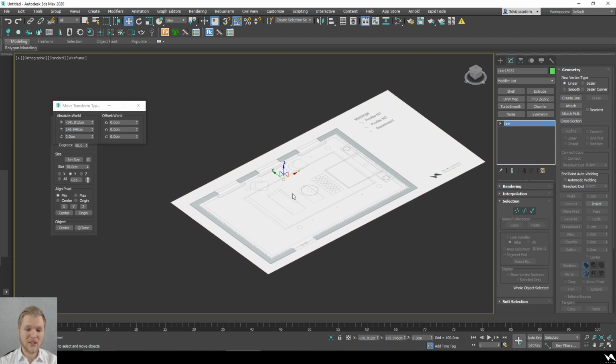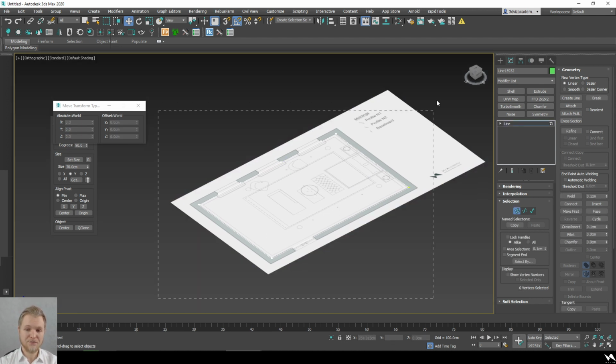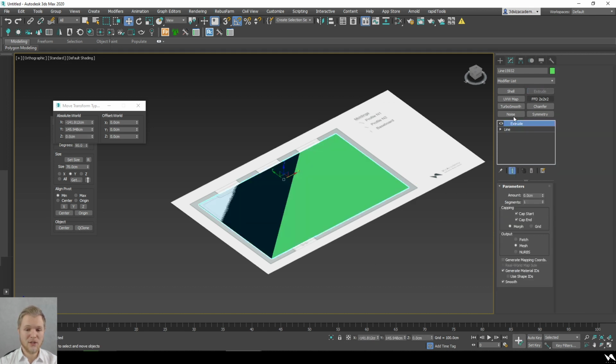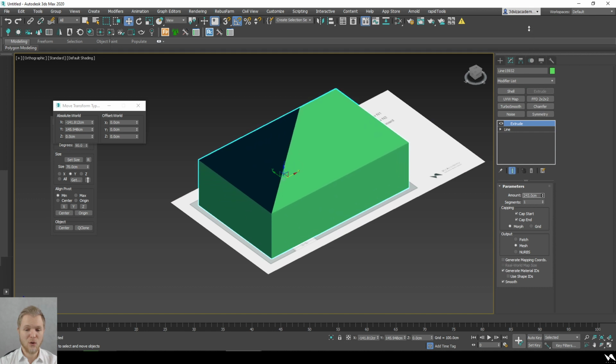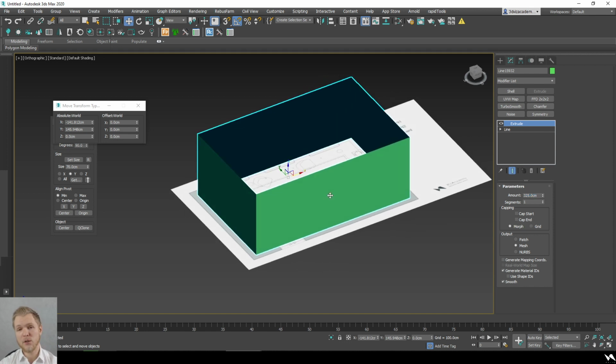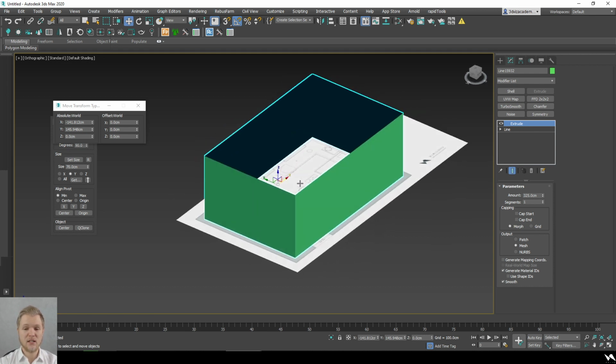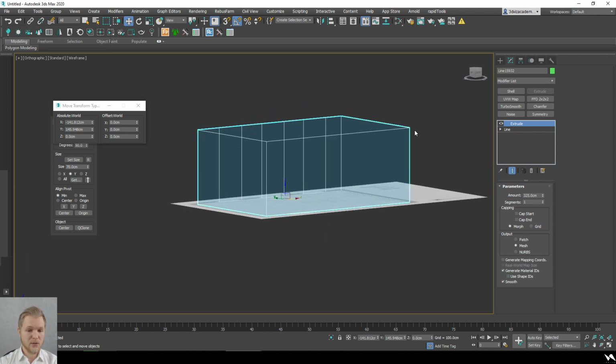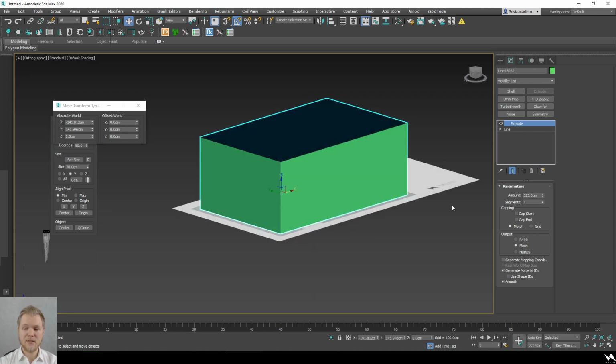So once you create it and outline all of those key points in your room, I left out the doors intentionally because I don't need to add them in. And next step, what I'm going to do is just simply extrude this whole object. I'm going to set 3.5 as my room's height, and I'm not going to cap the bottom or the end of it because I don't need to. So as you can see, we already have our base for the model.